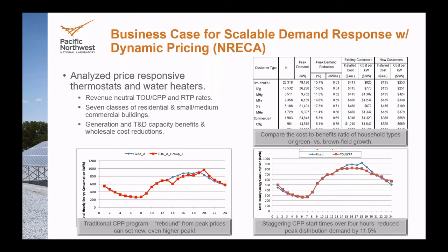And what this was doing is, if you're not familiar with time of use or critical peak pricing or real-time pricing rates, it's sending out a pricing signal to your end-use devices or your individual homes and consumers, and either the user or the appliances themselves have some intelligence built in that say, this is the cost of electricity I'm willing to pay, this is how much I want, and submitting that back up to the system and saying, I want 5 kilowatt hours at 3 cents per kilowatt hour. And the market will reconcile all of that with the price of the generation and the availability, and then send back a pricing signal or some type of incentive signal.